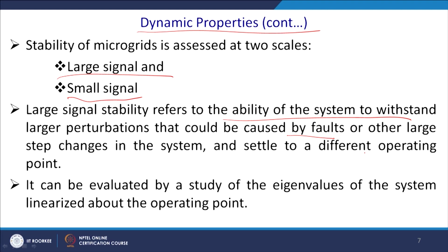Maybe once you have 100% loading, you fix the DC bus voltage at 48 volts. Once you throw off 50% of the load and you have generation, maybe you allow 48.5 volts as a new settling point, and that is allowed. So, you stabilize at another settling point depending on your convenience and within a band of control which you have accepted, and vice versa.